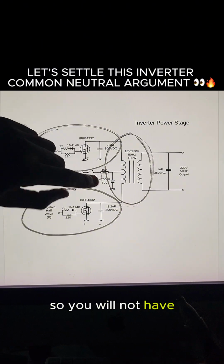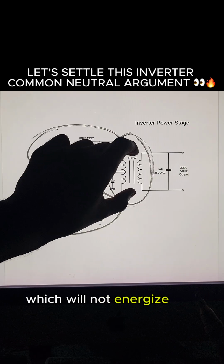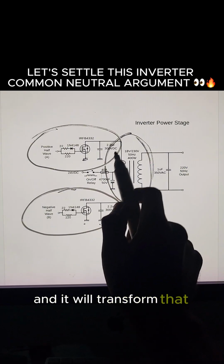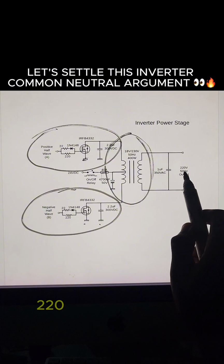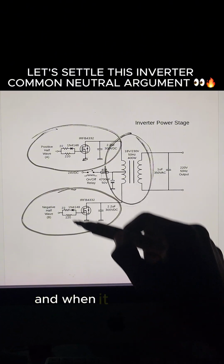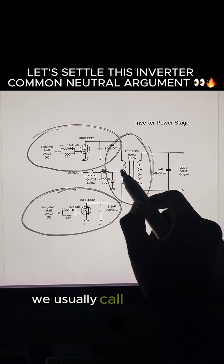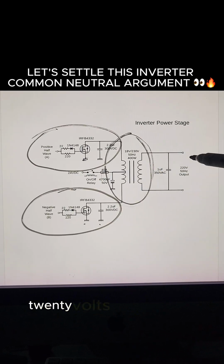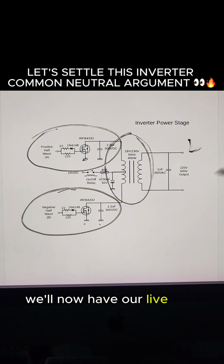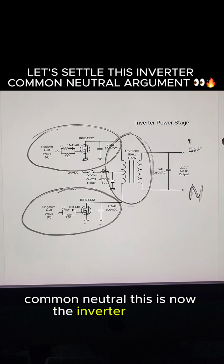So you will now have the positive of the battery terminal here and the negative terminal here, which will now energize the transformer. And it will transform that voltage from that 12 volts that we'll have here to 220 volts on the output. And when it does on the negative cycle too, it does the same thing. This center part, we usually call it a center tap. So what now happens, you see that we've generated our 220 volts on the output. We will now have our live and we'll have our neutral. So for all of you talking about common neutral, this is now the inverter output.